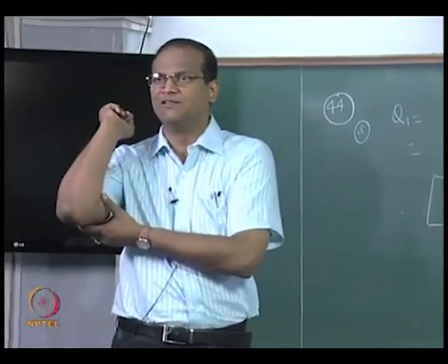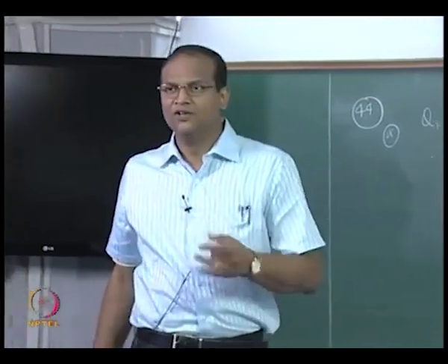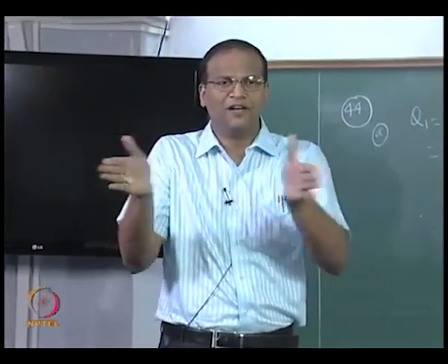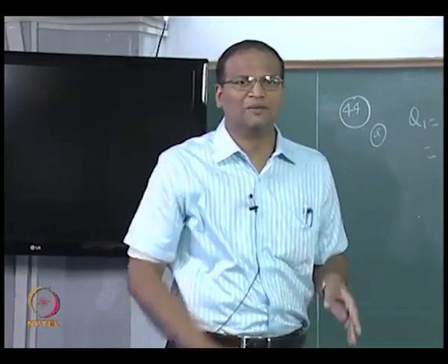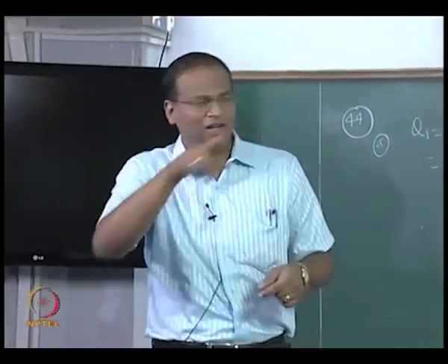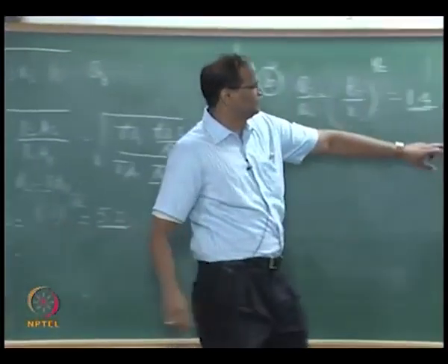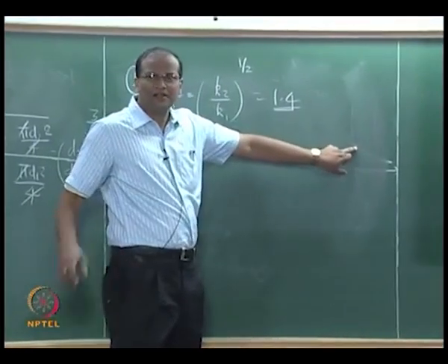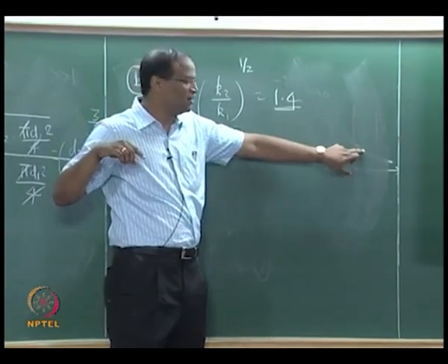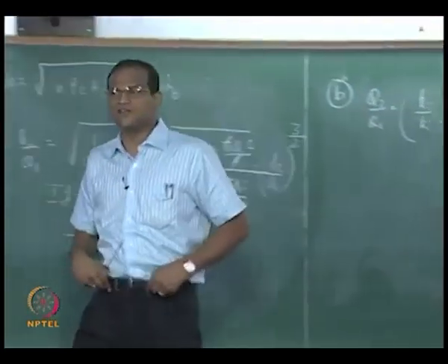So you can do some additional work. I don't normally do a problem like this, I do not have time now. That is, you have a fin set up and measure some temperatures, then you keep on guessing the value of thermal conductivity, it will give a theta versus x curve like this for various values of k. There will be only one value of k which gives a curve which is closest to the experiment, then that curve should be the best representation of the thermal conductivity. So that is basically what is called an inverse problem, okay.